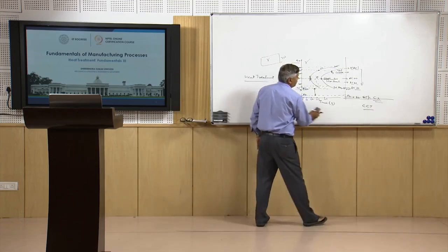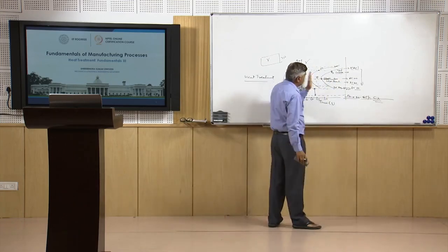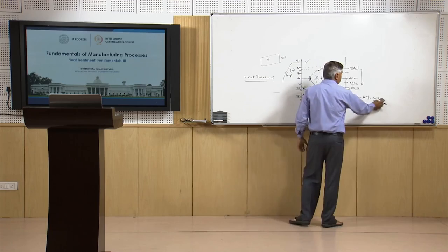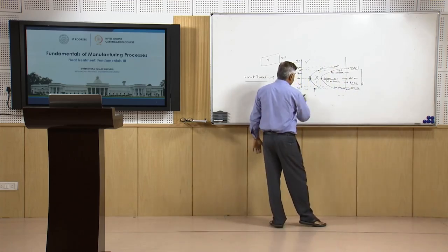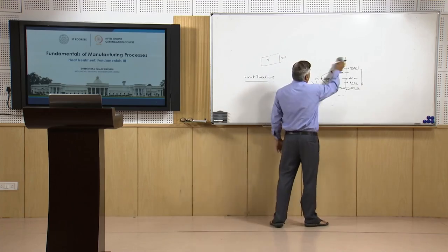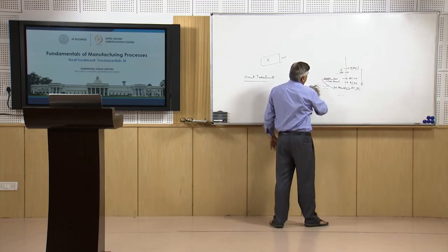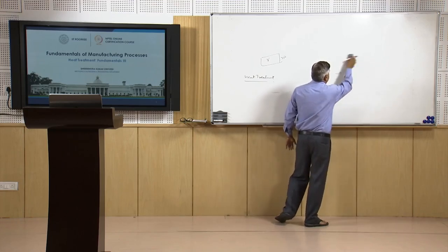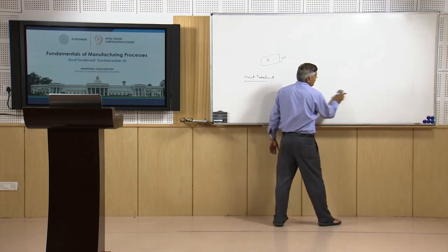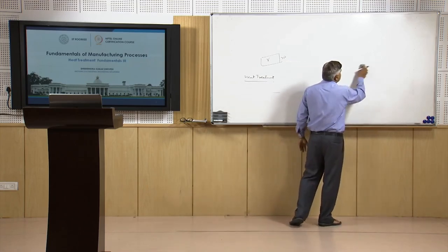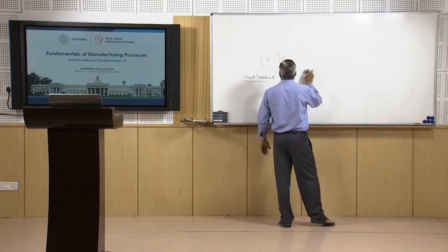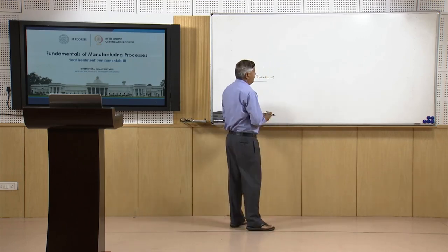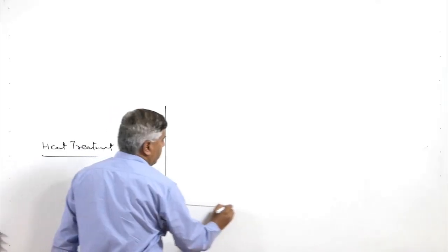Now, let us superimpose the cooling rates, because these transformations correspond to constant temperatures, but what if the steel is cooled at different rates instead of being held at a constant temperature? The transformation diagram helps us see what kind of phases will be obtained if the steel is exposed to different constant temperatures in the austenitic state, but in practice we apply different cooling rates.